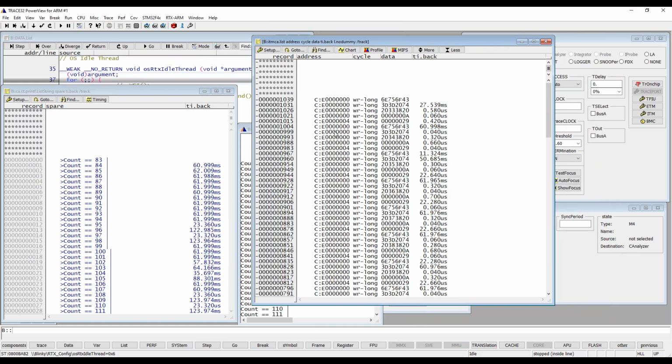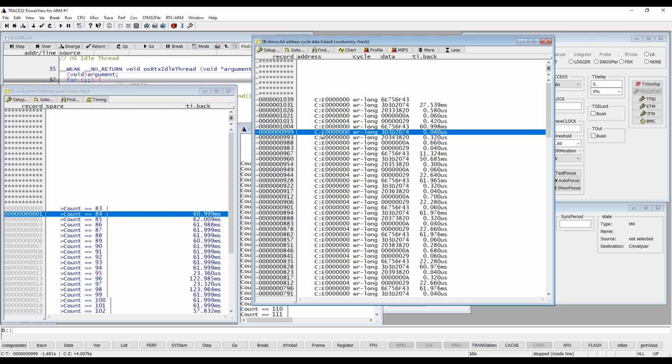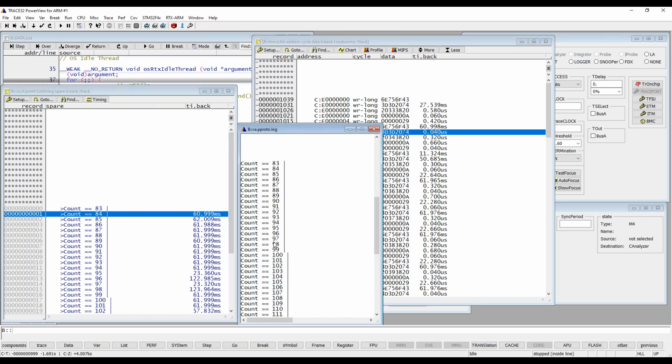So as you can see here, we are writing to some address E000, and that is channel 0, but I'm also writing something else to the channel with E004 at the end. That's another channel. So you can use all of these channels to separate your data if you want to. But when it comes to channel 0, I'm using that for printf. So that is what you're seeing here, more or less. But you can use it for instrumentation trace. So that is the ITM.